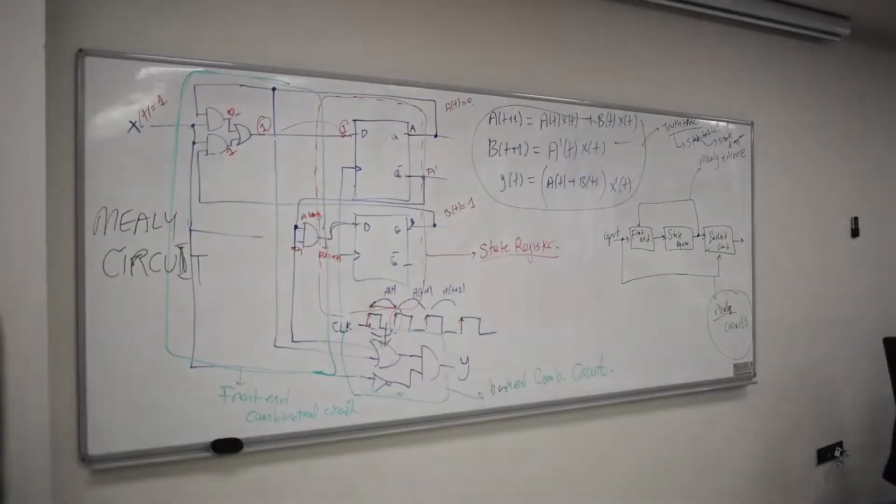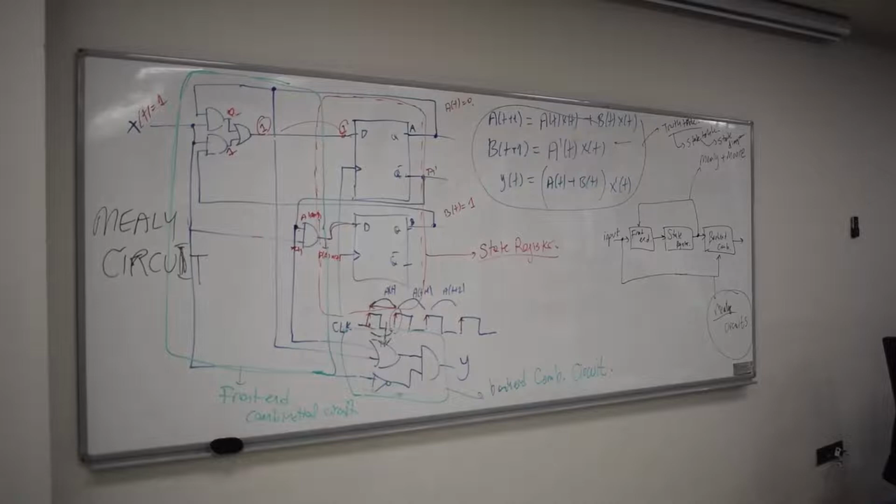This output says that at this particular time instant, this input had got one run of ones. It doesn't tell you the run length, of course. It just says that there is a run of ones. Maybe it's length 1, maybe it's length 3, maybe it's length 20. Okay? It says there's a run of ones here. And then 0, 0, 0, and then you see a one at the output. It says that I see another run of ones. Okay? In this case, it's length 3.